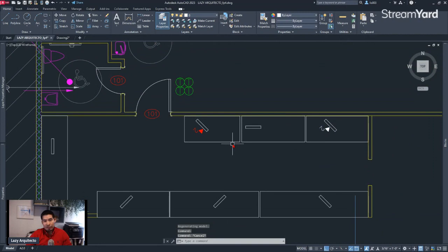However, there was a sixth step that we could do to simplify this process, which was make Autocad not ask for the input or the number for the attribute. Why? Because my client, like I said, 90% of the time he used the number 2.